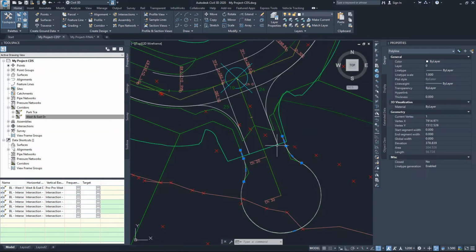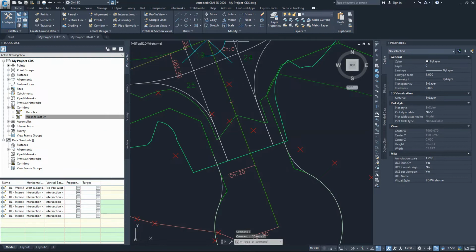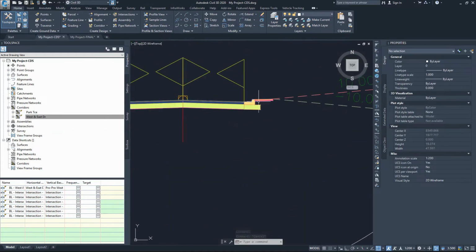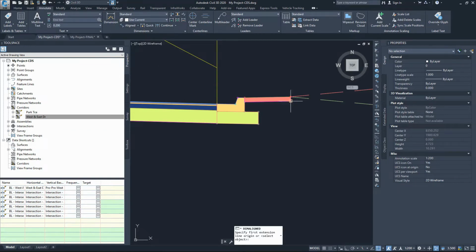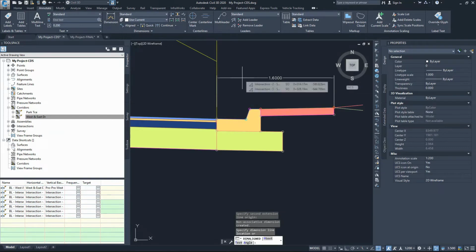So our alignment should go in line with this, should go all the way here on the inside, turning around to draw a curve all around and then come match that existing curve. So all I need to do is offset this line by the same distance, and that distance should be, if you look at our cross sections here, the distance from this line all the way to that line there. So if I measure that distance from here to there, it's 1.6 meters.